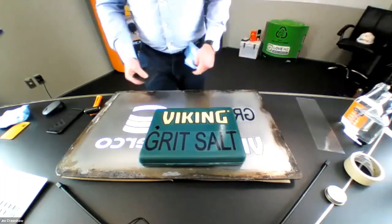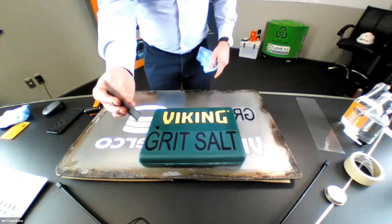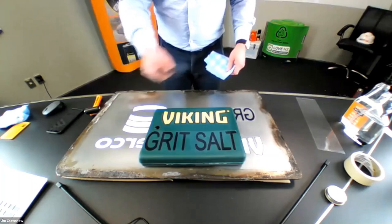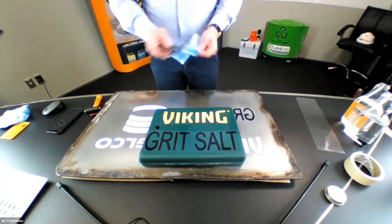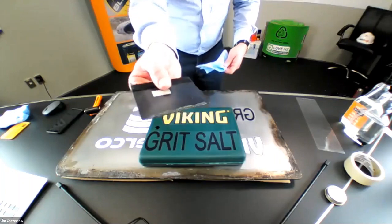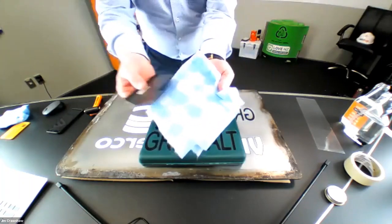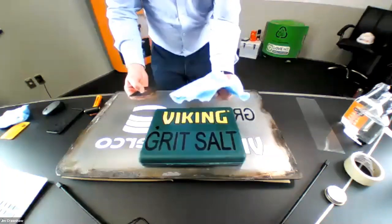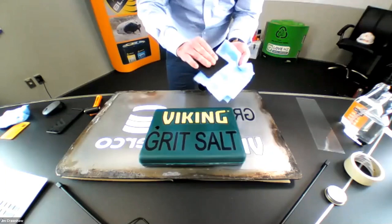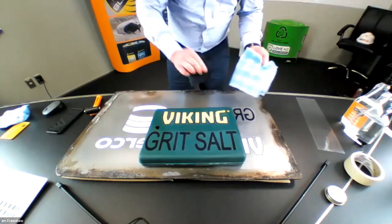And you'll notice the adhesive start to globule. And just using a thin or a sharp plastic squeegee again, I'm just going to scrape that adhesive straight off. So you just work across like this. I'm trying to show it on the camera here. Maybe you can see a bit of goo, and then just depositing it on a throwaway rag like this here. So I'm scraping right over the graphic, and that just really quickly pulls off all the adhesive.